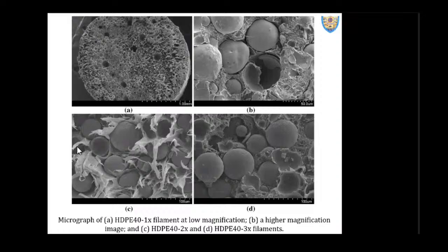But if I have such entrapped air, my density will still go down, and probably I may achieve much more than what these microballoons can do individually. Specifically in compression, damping, cushioning, energy absorption, and impact, these voids will play a major role, and they will absorb some of the energy, and energy enhancement can be seen. And you can justify that way also. So if there are any voids or cracks, don't say that we got a perfect sample, which is not possible, because our manufacturing methods have variations, and those variations will reflect in the samples.